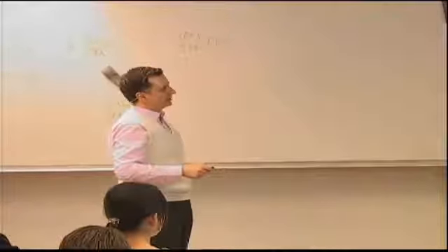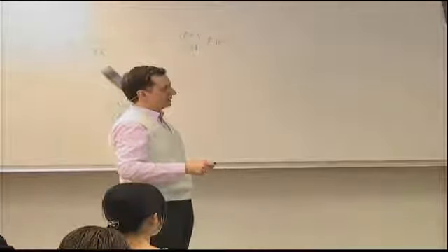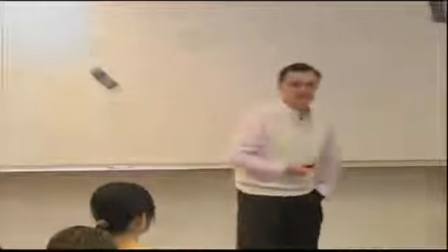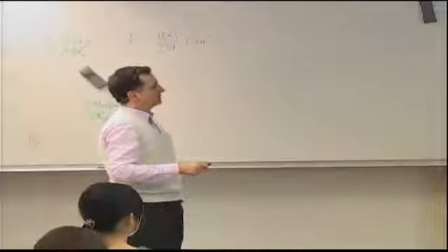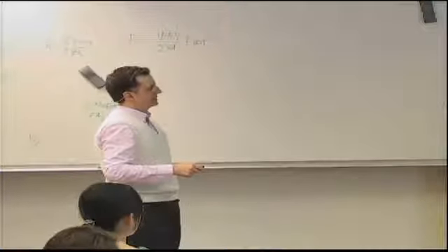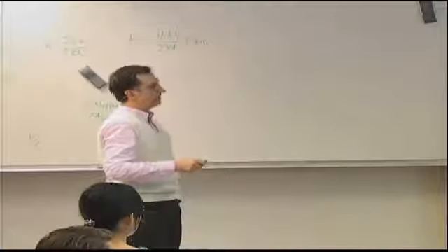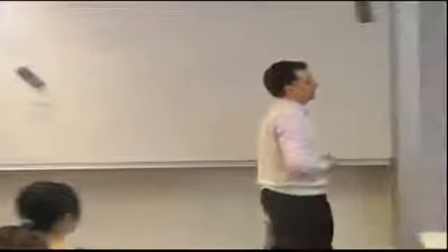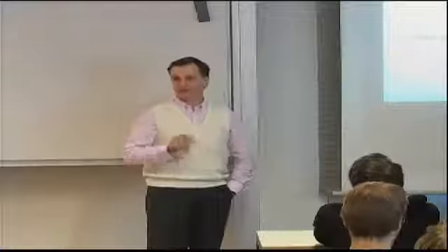So we take that equation and remove all the dependence on y, which means all derivatives with respect to y are 0. We are left basically with the D11 term for the flange, the unknown out-of-plane displacement w that the flange will go into during inter-rivet buckling, and the applied load Nx, which I call N0 being minus Nx, so if N0 is positive, I'm under compression, and again the second derivative of w. In fact, since there's no dependence on y, I can change the partial derivatives to total derivatives, but for consistency I keep them as partial derivatives.